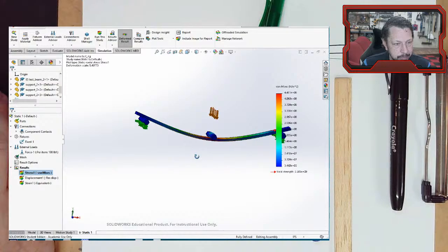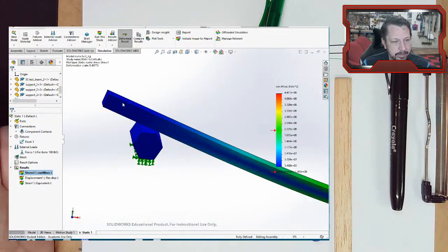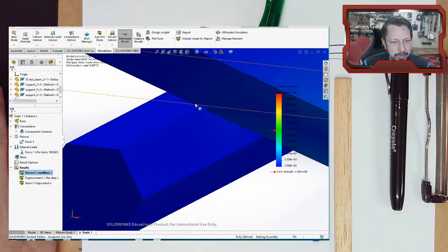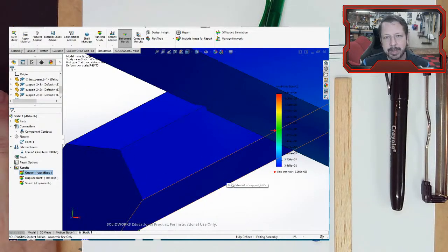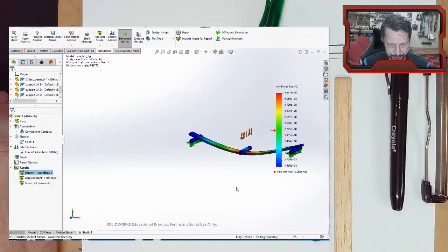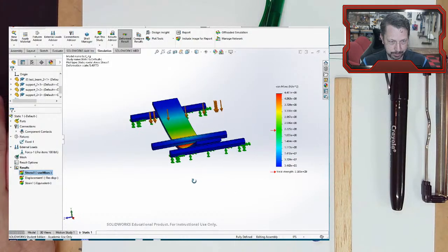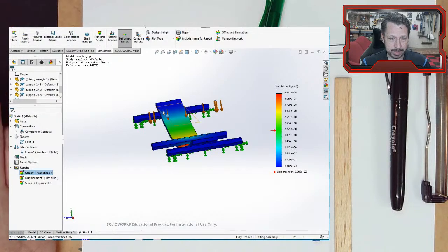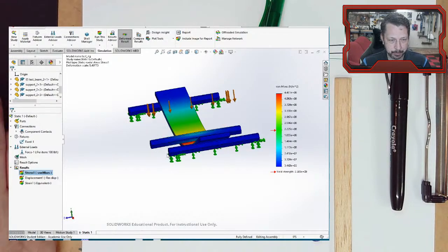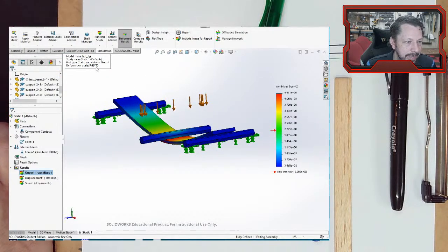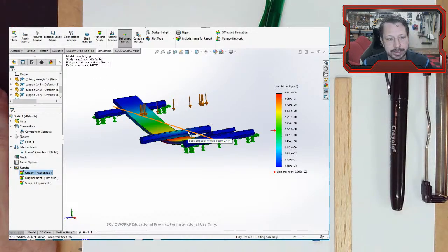So here's the shape we were expecting to see. There's that, it kicks up. Now there is a little bit of collision, penetration right here on this corner. I'm okay with that. We're not really worried too much about this geometry, but the way I loaded the loading beam, I put the load all the way across there, and you can actually see a little bit of curvature in the loading beam. Now we're magnified 5.5 times, it looks like, so there's probably not that much.